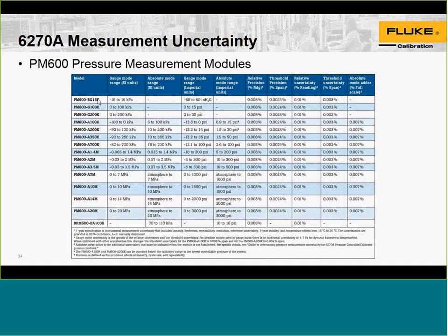A question did come in, and the question is: is the pressure pump included with the controller? Well, for the 2615, yes. Everything needed to control pressure, no matter if it's pneumatic or hydraulic, is inherently in the instrument. Except for the gas devices, where you need supply pressure or vacuum externally. We have other products that have self-contained vacuum and pressure sources.